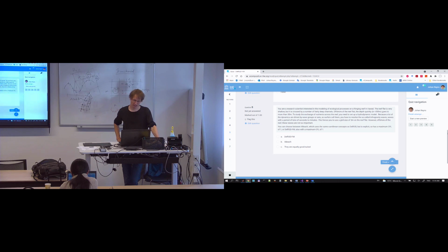Yep. Well, the answer is twofold. Actually, you have channels on the reef, and these channels are fairly deep. So, small grid cells and deep water depths are not friends of each other if you work with CFLs of 1. So what you ideally want is that you have your reef flat itself at high resolution, but if you go to the reef channels, that you can coarsen them somewhere so that you can raise your time step. And then offshore of the reef, there you only have to resolve wave-driven and tidal currents. So you don't need that 5 meters there.